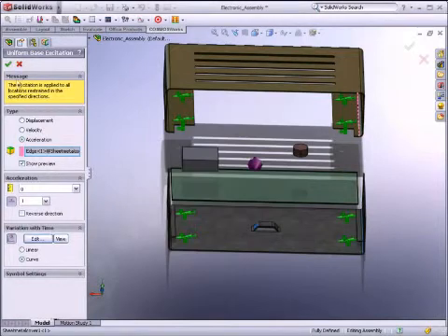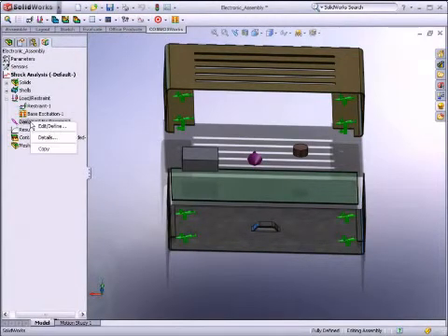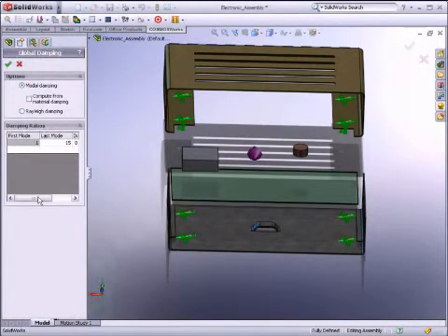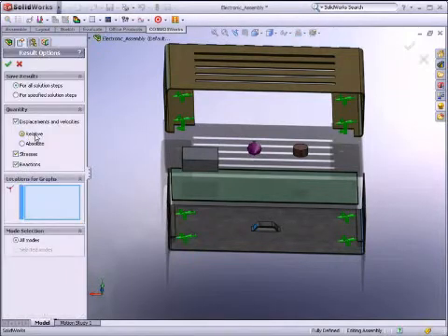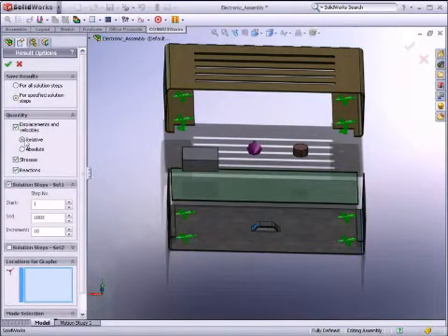You can apply global damping to stabilize the model. Our results options are customizable so that we can meet our non-standard information requirements. We are particularly interested in how the chip on the PCB will react to our dynamic input.